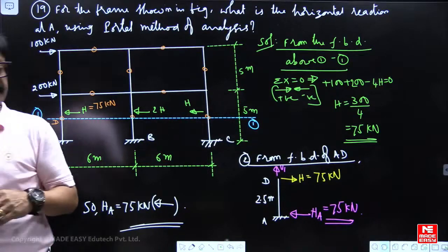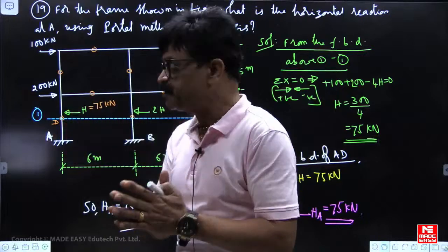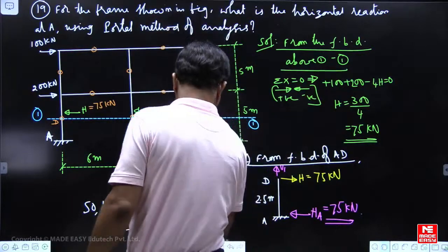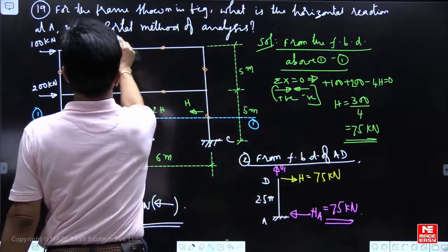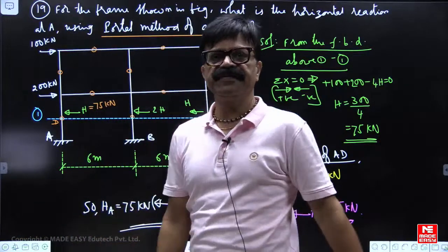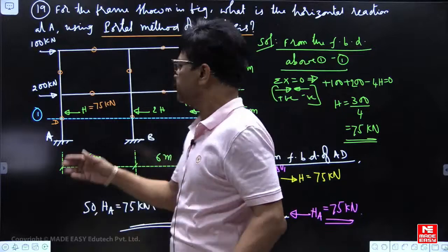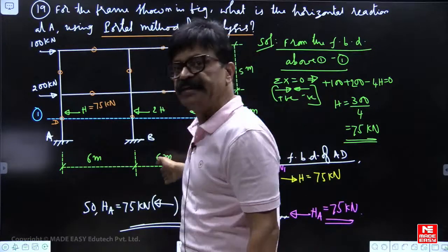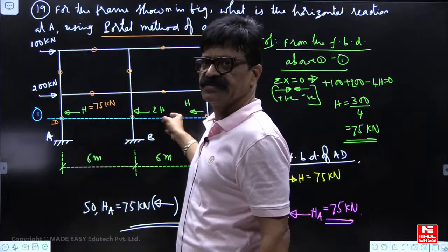Okay. Interior column will take twice that of exterior column is the assumption in the portal method. Portal method of analysis, two assumptions. POC at midpoint of each beam and column. Suppose there is one more interior column, H, 2H, 2H, H, like that.